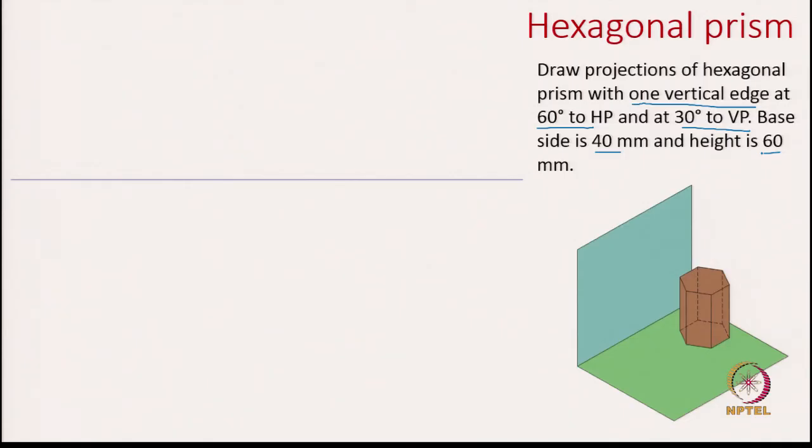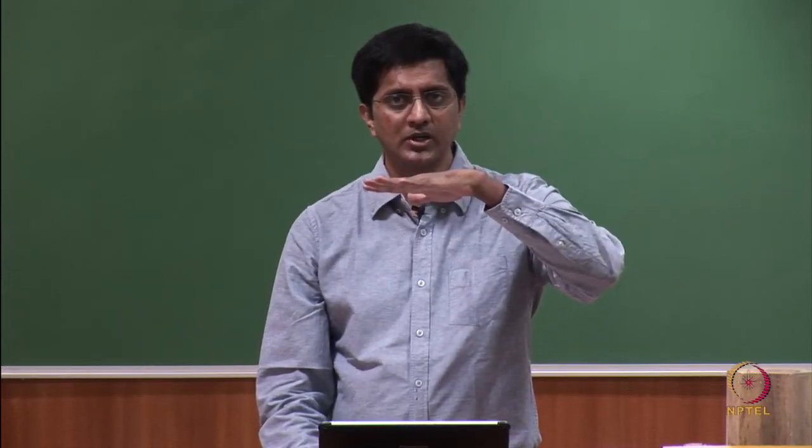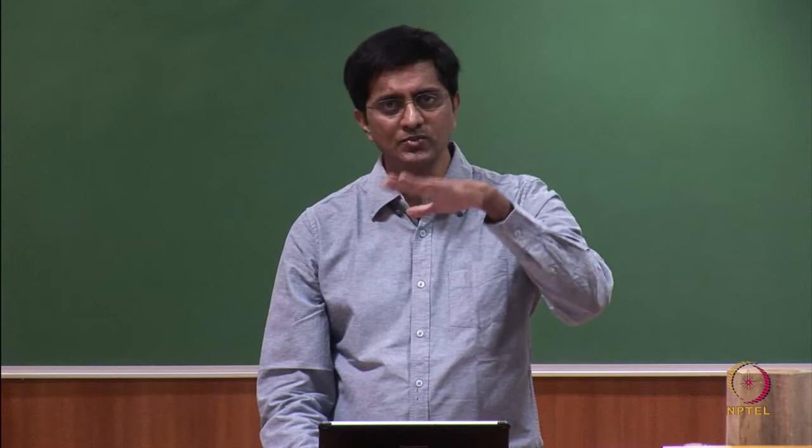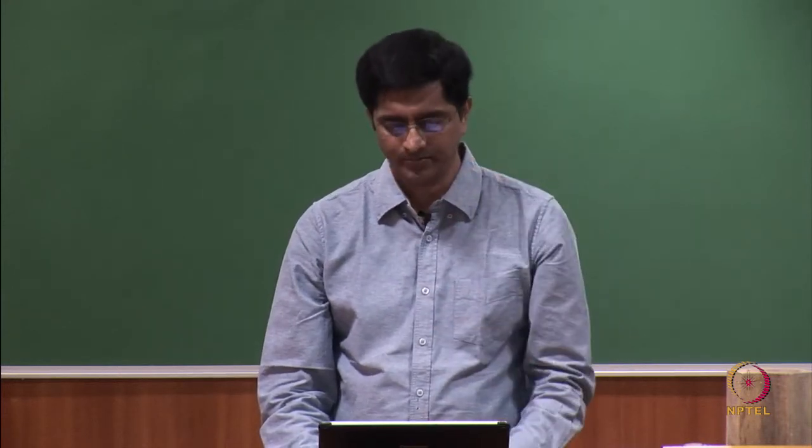So, the first step is of course the simple orientation, and here do we want to start with the front view or the top view? The answer is we want to start with the top view. The reason being, in the top view what you see is a hexagon, because the top base and the bottom base, both of them are parallel to the horizontal plane.